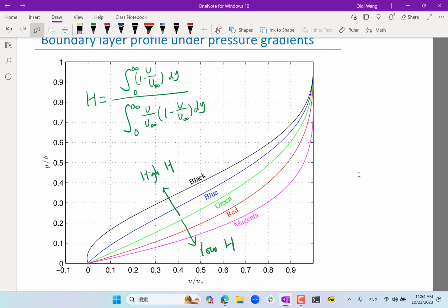So, let me say, in a lower Reynolds number boundary layer, right? Lower Reynolds number means viscous force is larger in comparison to other forces, right? The boundary layer is less prone to separation. And also in a turbulent boundary layer, there is more equivalent viscosity from the turbulence that also prevents flow from separation. So if you want to prevent flow separation, viscous force is actually a good thing.